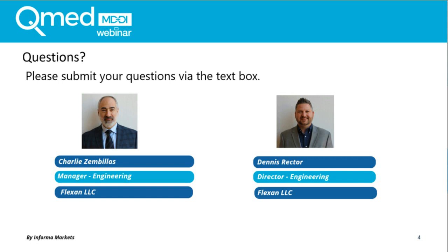So again, that would be an application-specific question. Silicone generally doesn't have a propensity to tear just by the nature of the raw material. I've seen walls as thin as 20 thousandths or 15 thousandths on silicone extrusions with no problem.